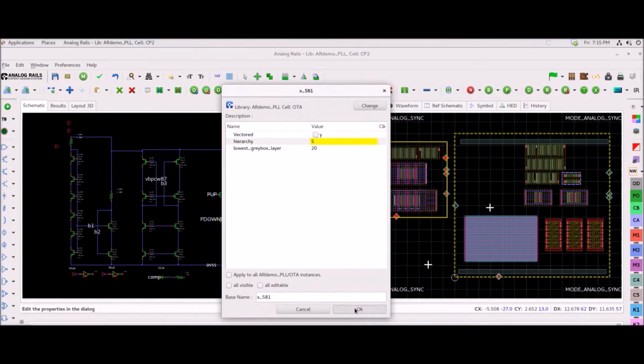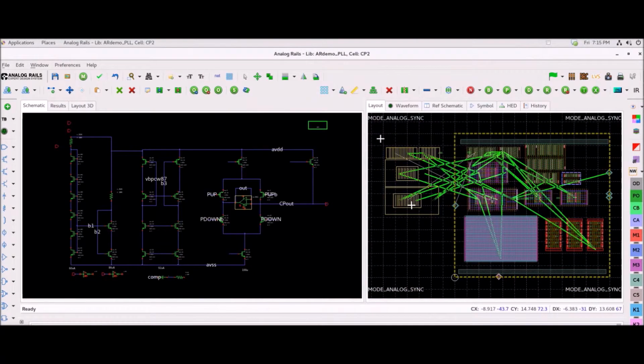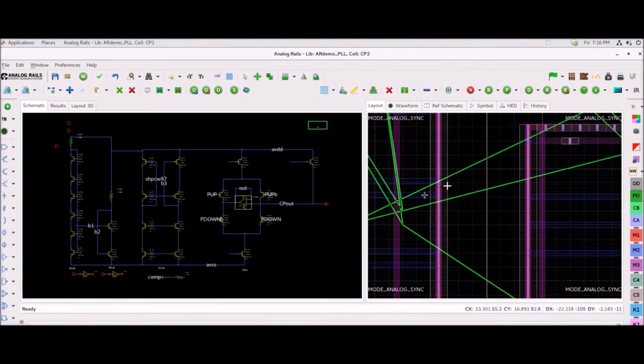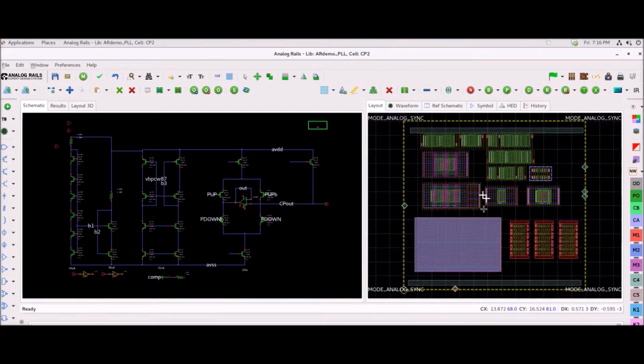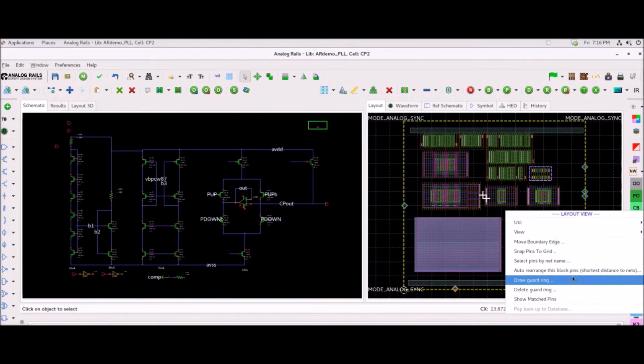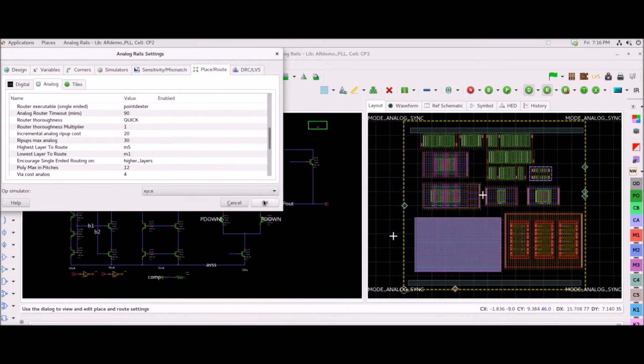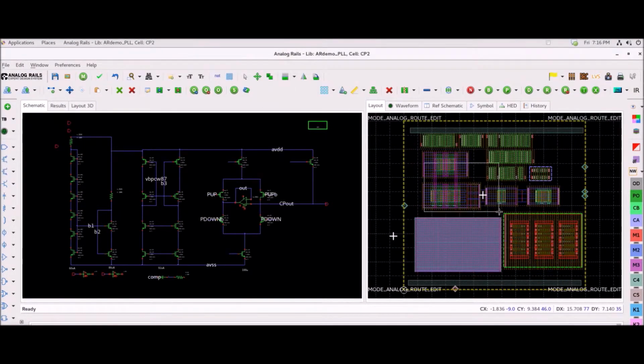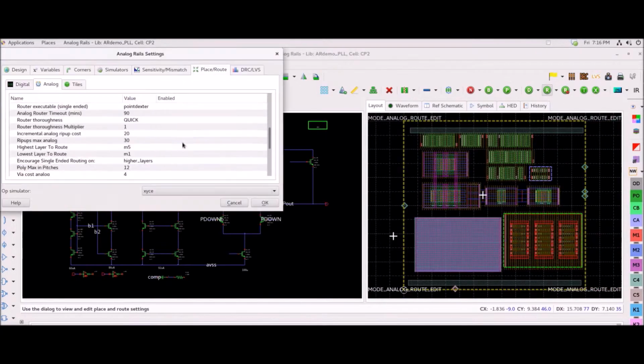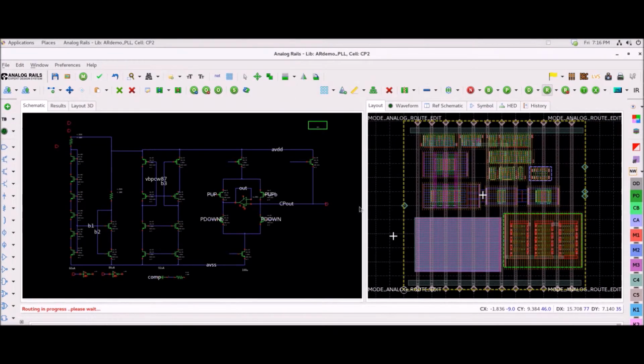Same thing. And we situate it within the charge pump, and then we're going to add the horizontal power supply trunks, and then we will automatically route it. And you'll notice once again that we never cause mismatch in the differential pairs nor differential routes. Isn't automation nice?